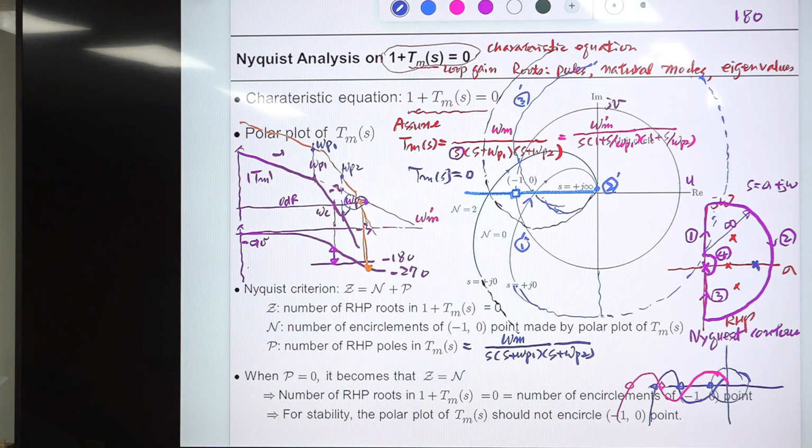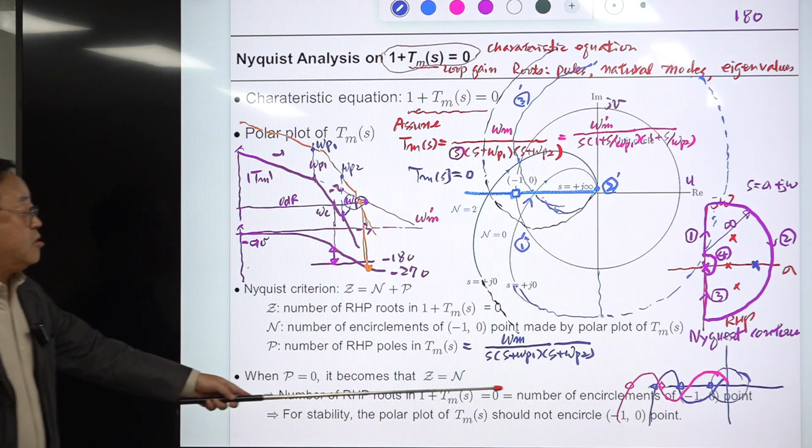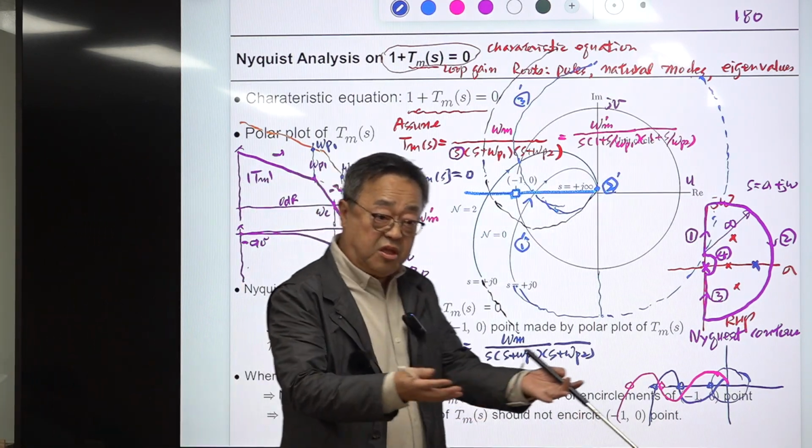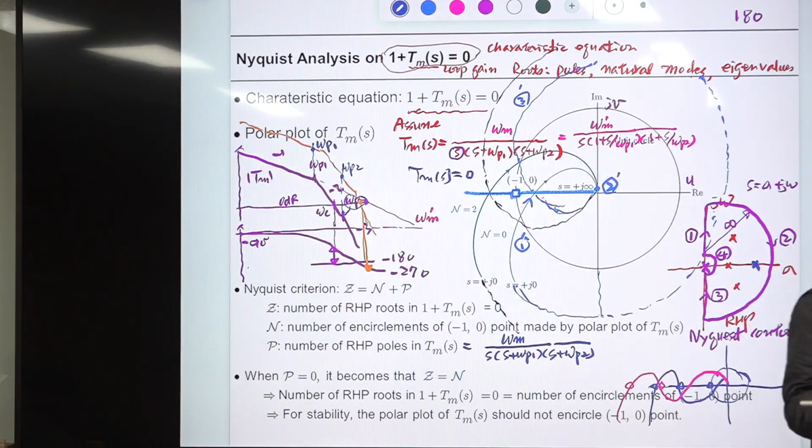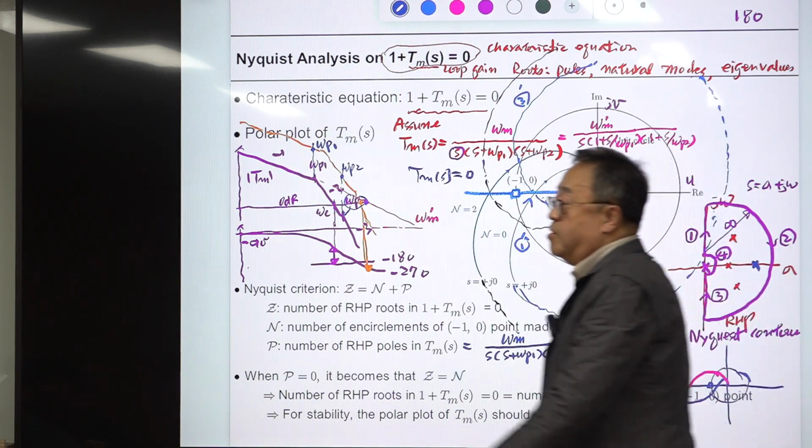Okay. Anyway, a conditionally stable or conditionally unstable system is the worst system. I told you that this system is worse than an unstable system. If you know the system is unstable, then you will fix the problem. For this conditionally stable system, it can be stable in some situations, and it will be unstable in some practical situations. You will meet that in the practical operation of the system. Okay, so that is very bad. Okay, but still this story is applicable to this system.